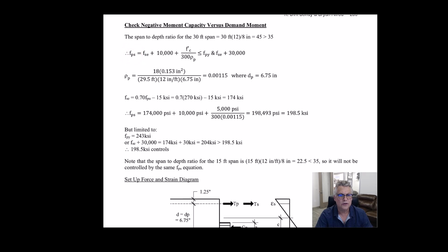So on the short side, this goes to 1, you get to go up to 60,000, and you'll have 30 KSI more usable stress at ultimate on the shorter side because you switched equations. Then you won't need the bonded reinforcement. But on the longer side, you end up needing the bonded reinforcement for strength, maybe. So anyway, we've seen strange situations like that.